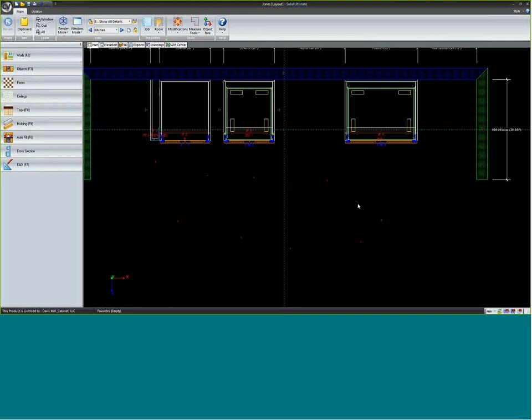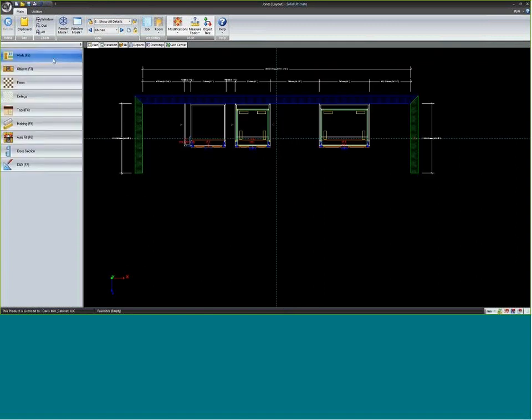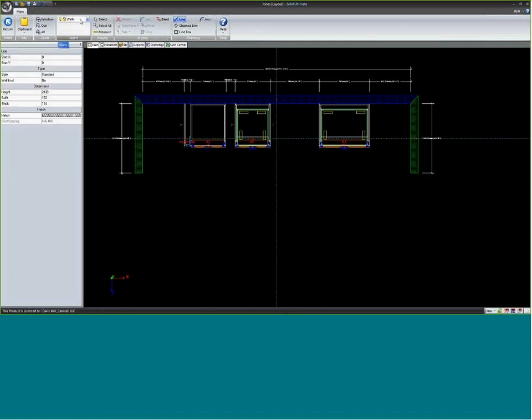Now, if I want to clear them completely, this ruler button will do that. It completely gets rid of all my snap marks. So, snap marks are a good way to place hidden walls. Although yesterday we talked about in the wall mode this construction line.